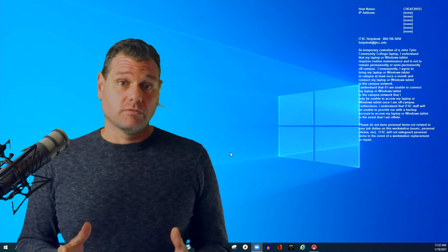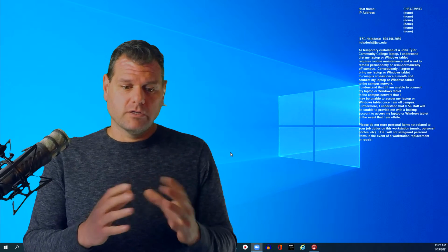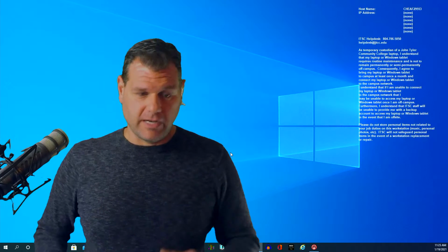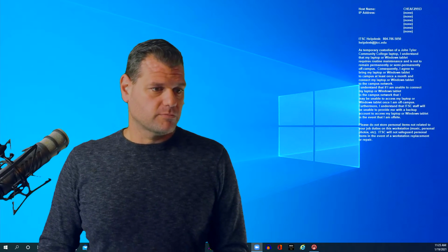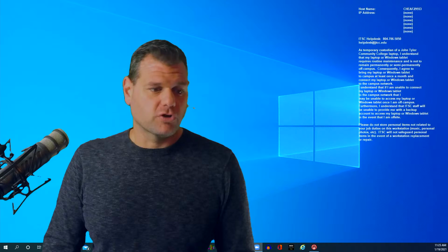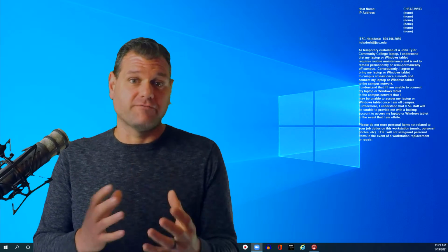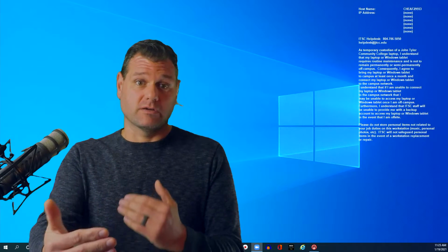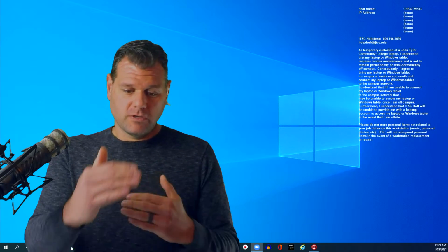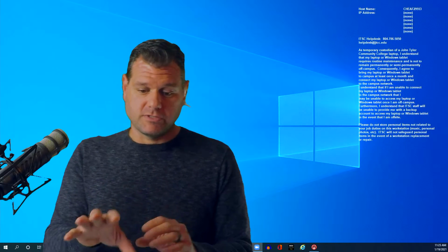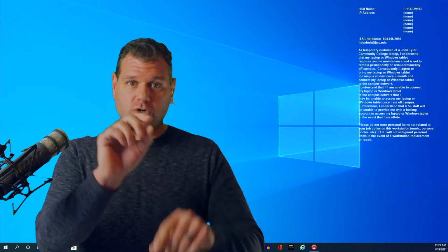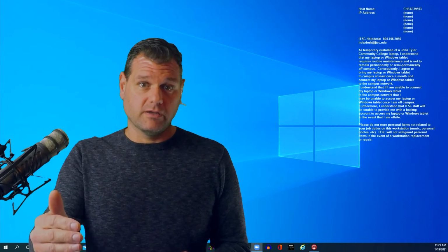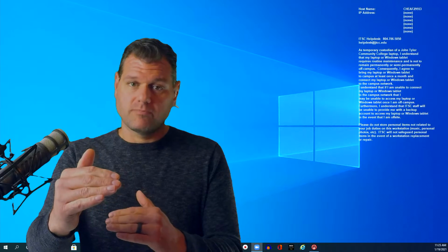So Joe, the finish line for your master is always going to be on, irrespective of whether the zone is activated or not. Yes, if it's unconditional, you could have a condition on there. The reason they typically use these is when you want to turn off a section of logic that is, let's say, a fault. Let's say something happens and you have a set of pumps or motors running that is dangerous, something that is going to hurt somebody or mess a system up, right? You put those things within this zone and you say, okay, if this fault happens, I want you to go ahead and activate or deactivate this MCR master control relay or reset instruction, and you're going to go ahead and take all those out.